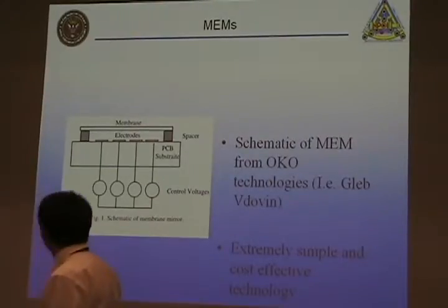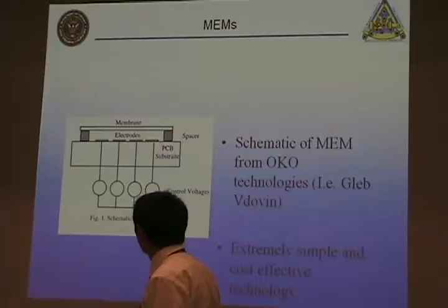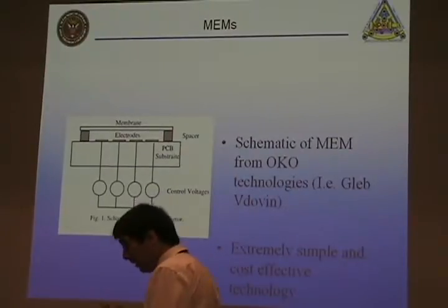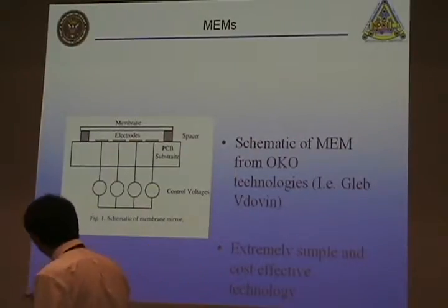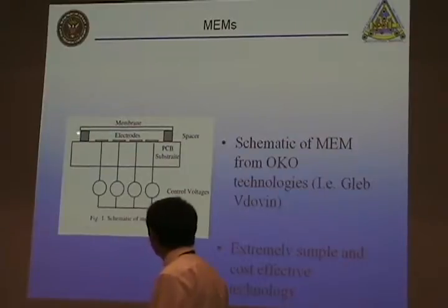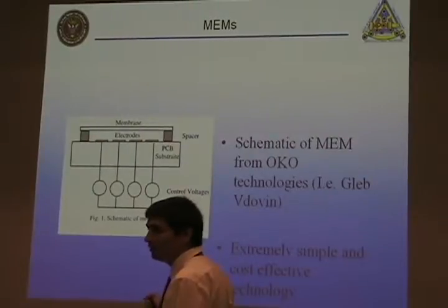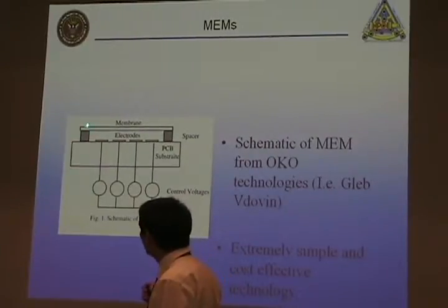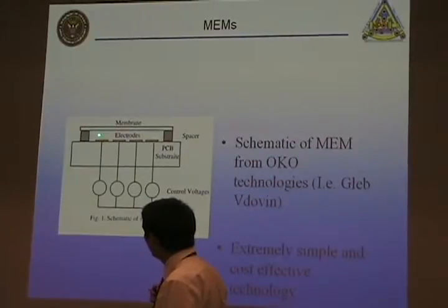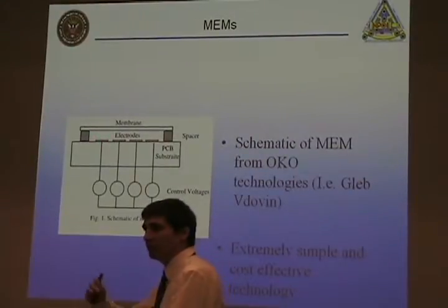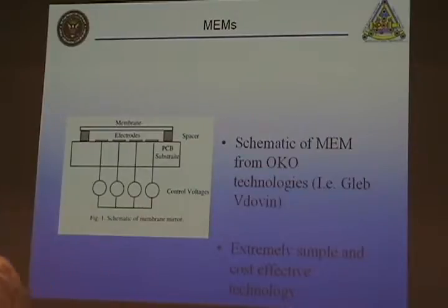Right. And then this is the other device that we've been primarily working with. This is a MEMS mirror. Basically, it has a very thin membrane with electrodes underneath. You apply voltage, and it pulls this membrane down. To use this device, you have to use it with a bias curvature, and then by changing the voltage from that bias curvature, you can get effective changes in the waveform.